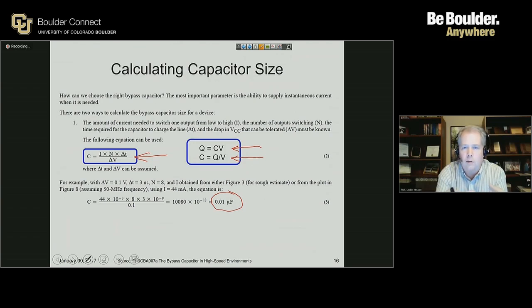They don't want to put extra capacitors on a board if not necessary, because it adds the cost of the capacitor and it adds the cost of adding that capacitor to the board in production. It's not just the BOM cost, or bill of materials cost, of the pure component that you buy. It's the cost in manufacturing of taking that component, putting it in a feeder that goes into a pick and place machine, putting it on the board, and then potentially dealing with yield issues because the part didn't get soldered correctly.